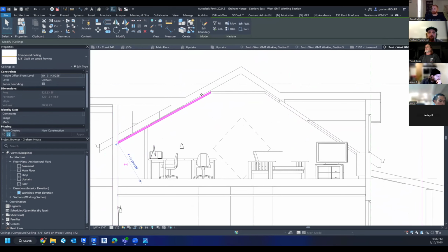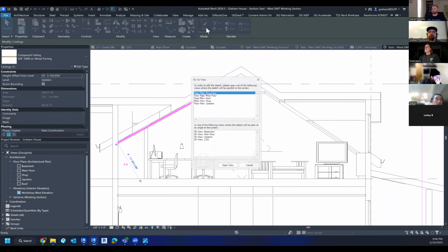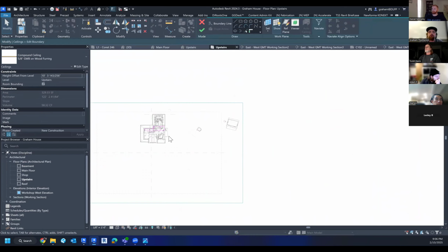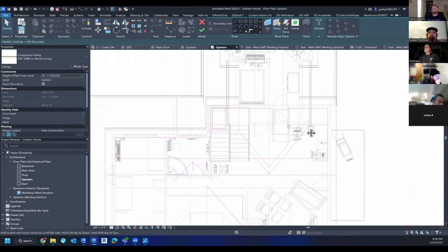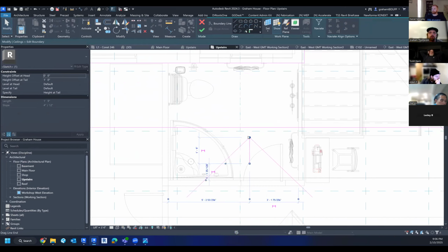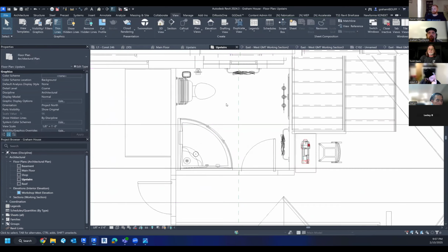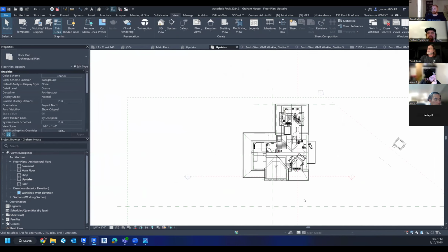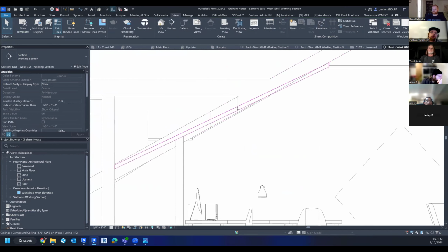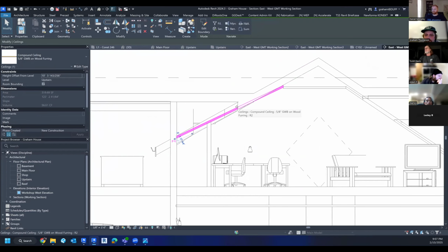Where I set a plane, then this is a little different. When you're in ceilings, it actually wants you to, here's your ceiling, and if there's a slope to it, you've got this slope arrow, and whatever the distance of the arrow is, like if I change this from 1.9 to 2 foot, that actually changes the pitch of my roof. So it took a little bit of guessing and checking to get that right. But you can see that pitch is now all screwed up for that ceiling. So same thing though, right? You can tackle it piece by piece and then put it together.